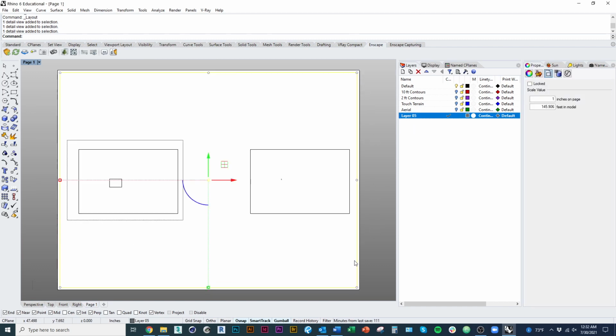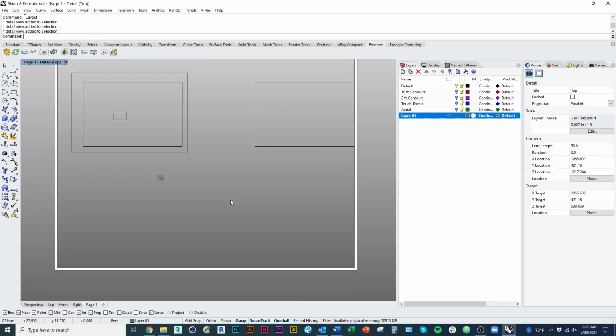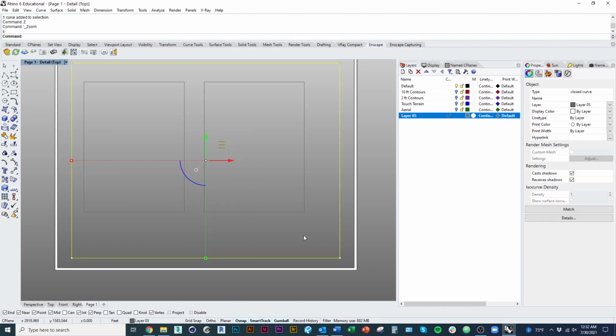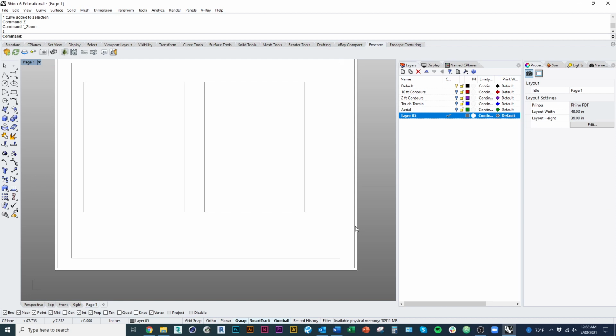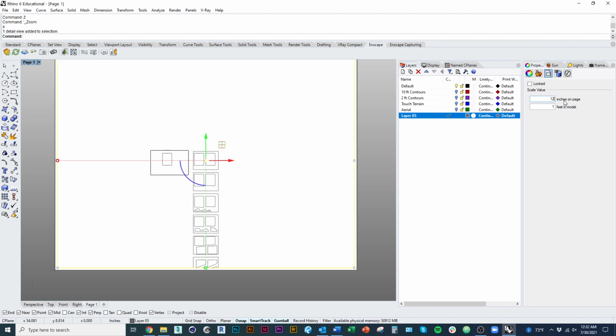So I would click on the detail window, which is like my little window into my Rhino print space, my model space. And I'll go, let's see, where am I? Go way into here, I think. Okay. And then I'll double click to exit and I'll select the detail window and I'll type 1 foot on the page equals 12 inches. 1 to 1.